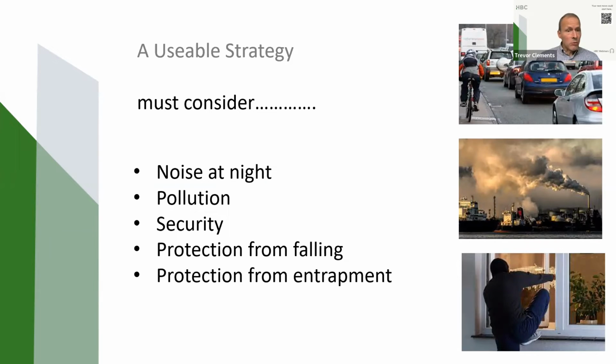So by accessible, I'm talking about windows within 2 meters of an accessible level surface. As you'll know from approved document Q, that correlates with that. But also windows that are adjacent to low-pitched lean-to roofs that are themselves within 3.5 meters of ground level. So if you've got windows like that, then you have to incorporate some sort of guarding or restrictor to prevent anybody creeping into those bedrooms in the small hours.